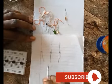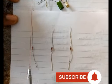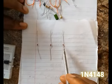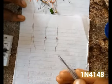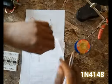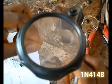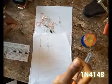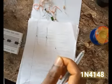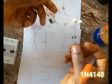Now we have a number of them. This is how they look. Zener diodes generally look like this, but I'll quickly mention something. There is one of them known as the 4148. I don't think you'll be able to see the number, but if you want to be sure of the number written on it, you could get a magnifying lens like this and put it under. Now this one is actually a 4148. It's not particularly a Zener diode. The 4148 is more like a PN junction diode, just something like this.